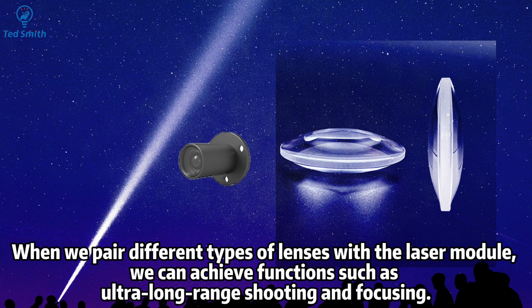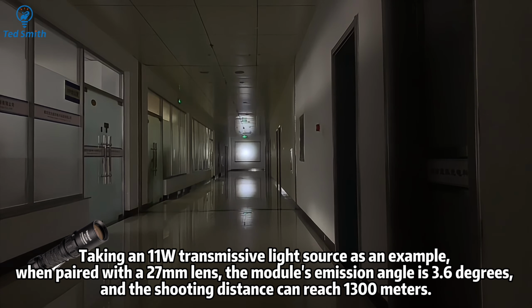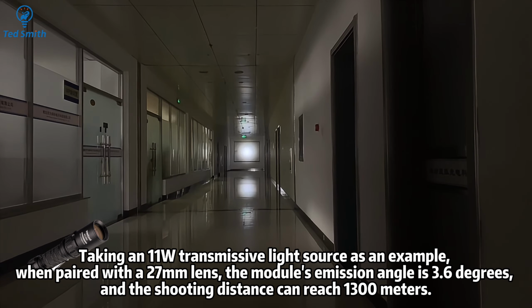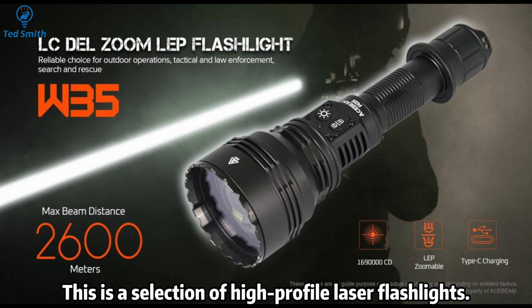When we pair different types of lenses with the laser module, we can achieve functions such as ultra-long range shooting and focusing. The larger the diameter of the lens, the stronger the focusing ability and the longer the shooting distance. Taking an 11W transmissive light source as an example, when paired with a 27mm lens, the module's emission angle is 3.6 degrees, and the shooting distance can reach 1300 meters. When paired with a 55mm lens, the module's emission angle is 1.6 degrees, and the shooting distance can reach 2,900 meters. This is a selection of high-profile laser flashlights.